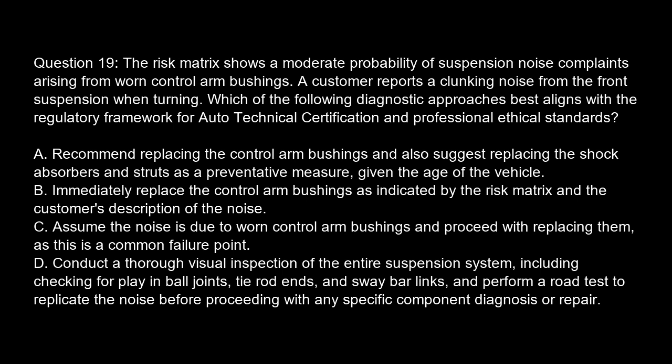Option D. Conduct a thorough visual inspection of the entire suspension system, including checking for play in ball joints, tie rod ends, and sway bar links, and perform a road test to replicate the noise before proceeding with any specific component diagnosis or repair.